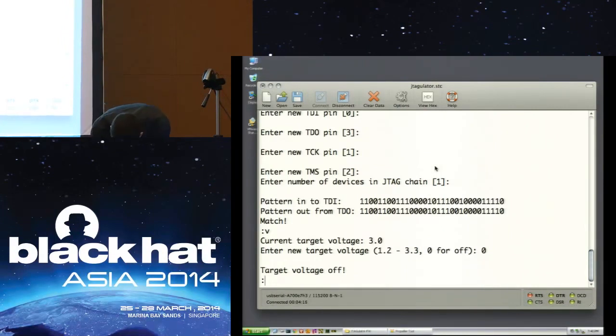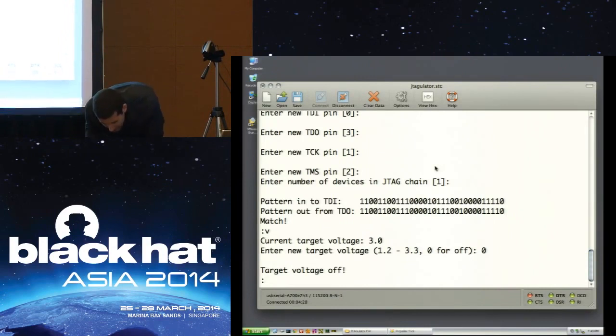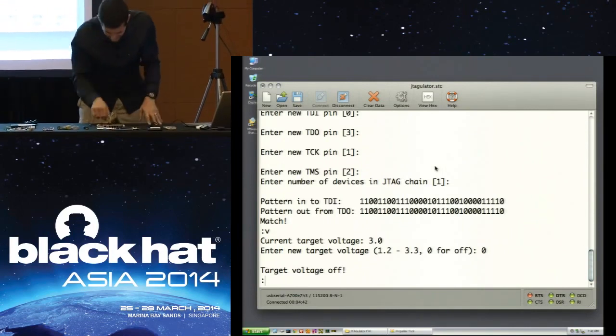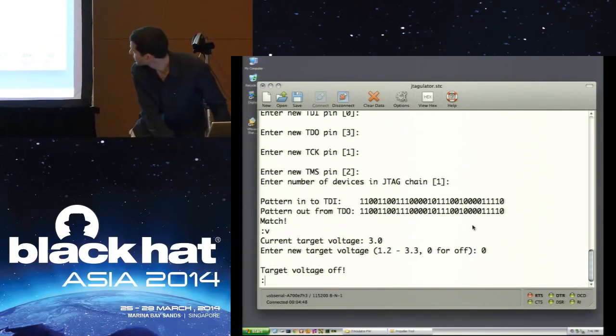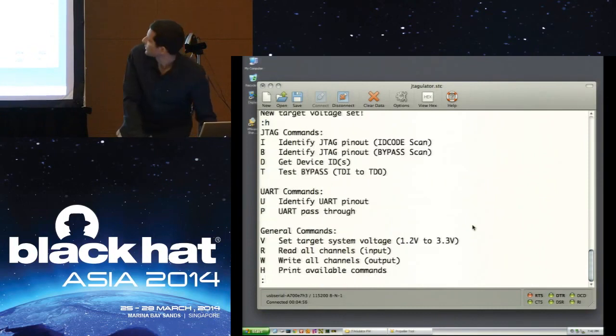So I'm going to connect ground, and then I'm just going to arbitrarily plug in these 4 pins from this connector. I don't know what they are. Get that one to fit in there. There, okay. So now I have the 4 wires from this unknown connector plugged into the JTAGulator. And, let's see, it's all powered on. So I should be able to now set the target voltage. I think the target voltage for the router is 3.3, but we'll see if that's right.